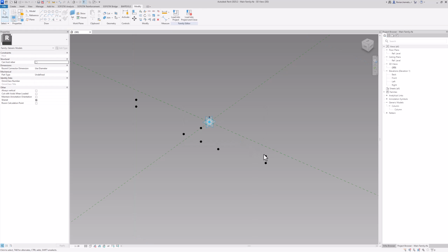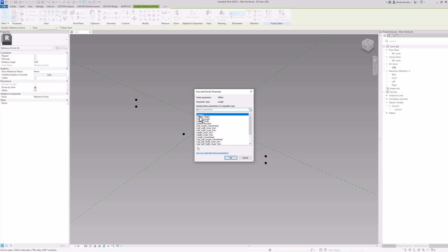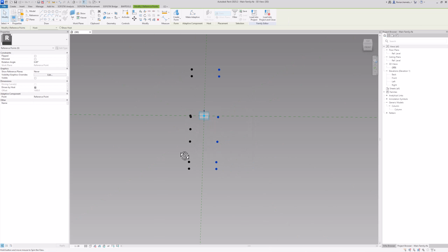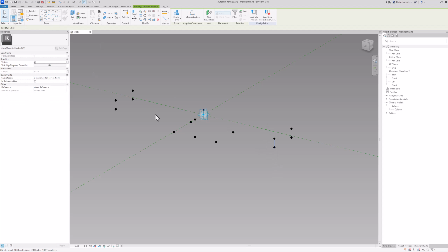Once I created all these points, I can now click at all of them and assign the offset, which is my column head length. Once I assign it, I have all my geometry defining points done. All there is left to do is to connect 2 by 2 together to get our reference geometry in the front and back of our column head.